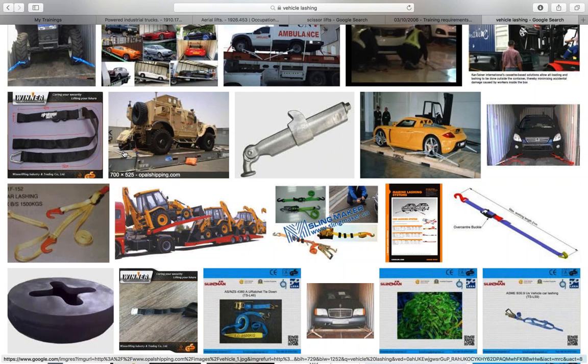Also, personal safety, right? It's as important as site safety. We need to make sure that we watch our actions because we don't want anyone getting hurt. What are we talking about? Wear close-fitting clothing, right, that may not get caught up. Tie back and secure any long hair underneath a hard hat before operating equipment.